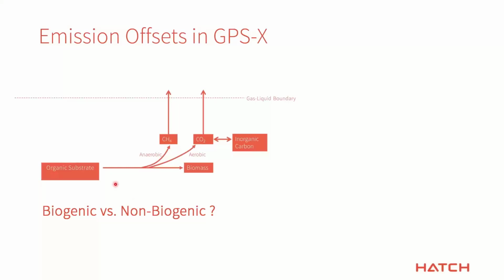So if our carbon that is coming in is biogenic in nature, then we can almost neglect this CO2 that is being produced due to biological oxidation. However, since methane gas is 25 times or 28 times higher in intensity, any methane that is being generated, even though it could be of biogenic nature, could still be contributing to the carbon emissions, and we need to check that out. So that's one important factor.